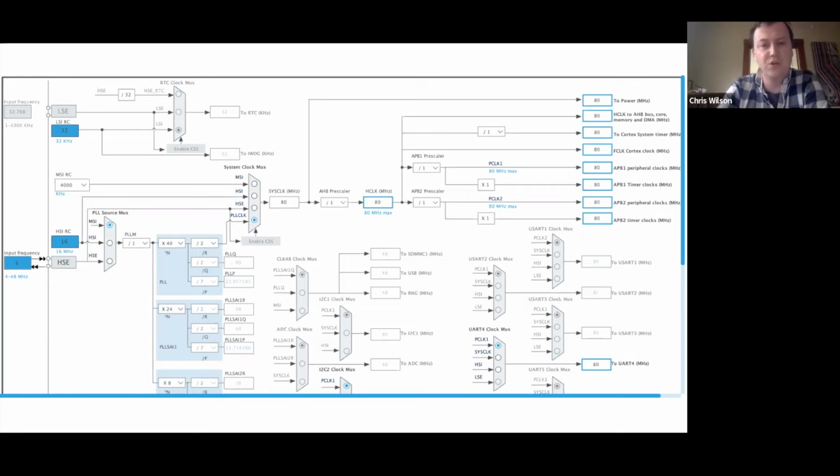And usually what happens is these chips will have an actual quartz crystal somewhere on them, either external or internal. And then they do various divisions or multiplications of that clock signal to get the various timers for different systems. So this chip ran at 80 megahertz for most things, but you could derive either faster or slower clocks for certain peripherals that needed it.